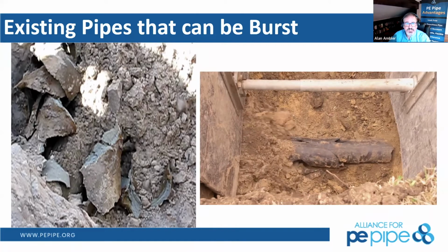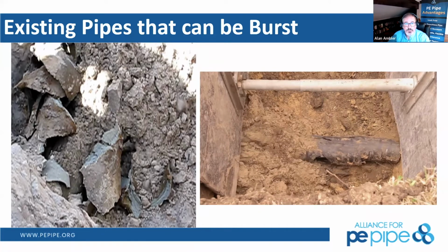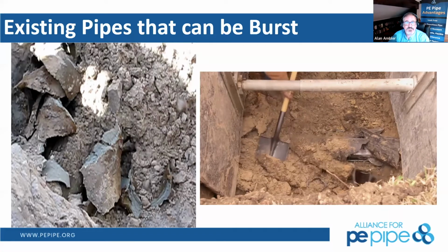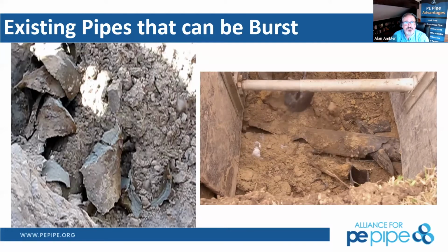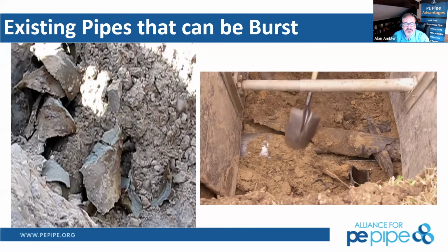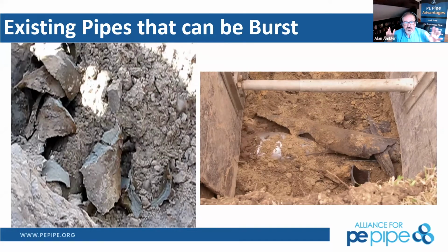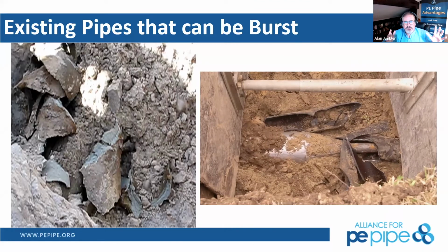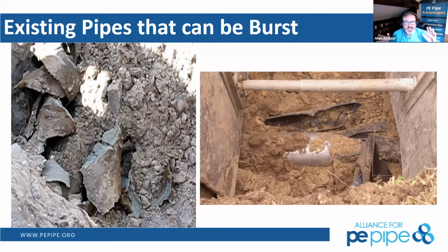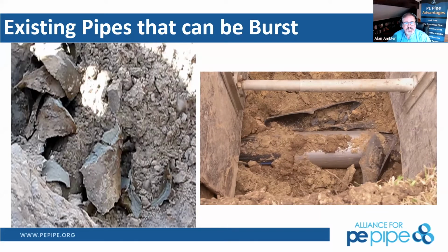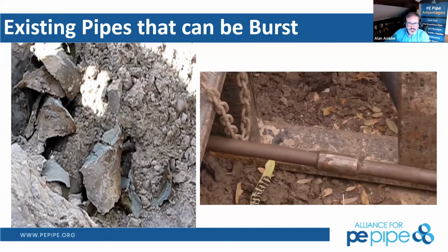This technology was developed by British Gas. They were replacing quite a bit of cast iron pipe within the streets of London and everywhere else. So they wanted to get as many techniques as they could to reduce that excavation. In the UK, they dragged a 3-meter section of sacrificial pipe in advance of the actual production pipe to look if any of those cast iron fragments were gouging the high density polyethylene, and determined that none were gouging it, and it's not a problem to be able to pull that through a metallic pipe in this manner.